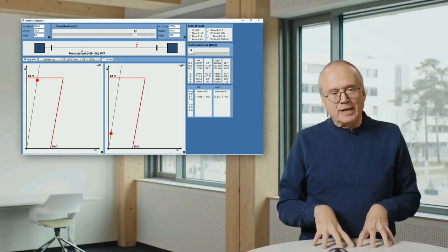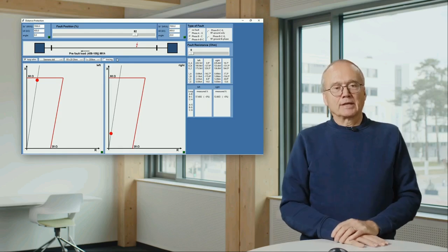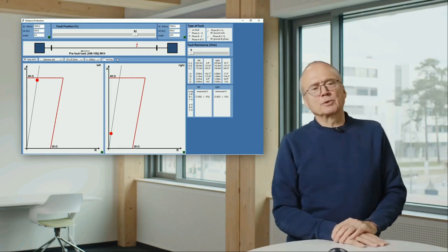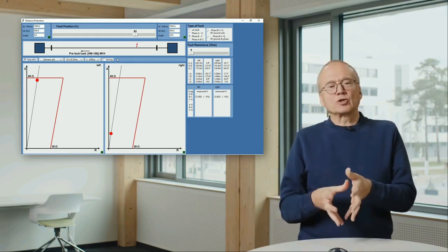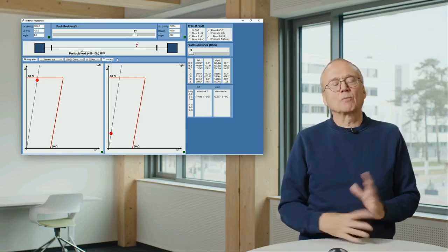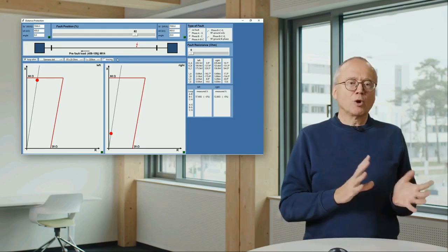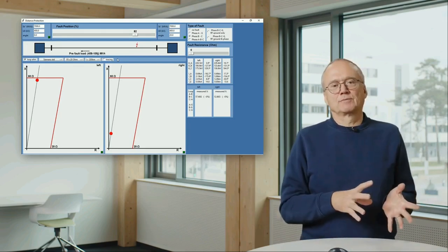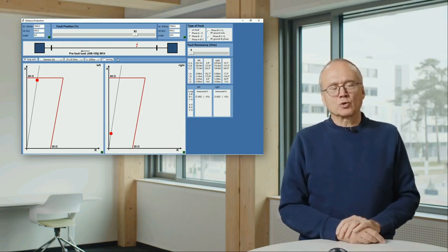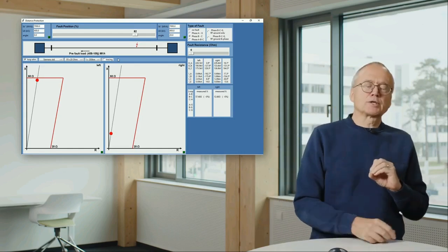As I mentioned, that is the behavior of the standard distance algorithms. Theoretically, it is not possible to really take into account and to compensate the effect of the fault resistance completely. Because if you write down your equations, you have more unknowns than equations. So theoretically, there is no possibility to solve that properly. But you can do some approaches.